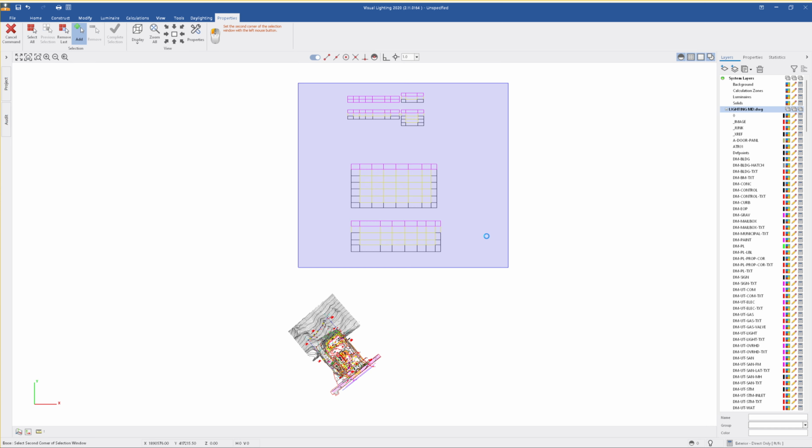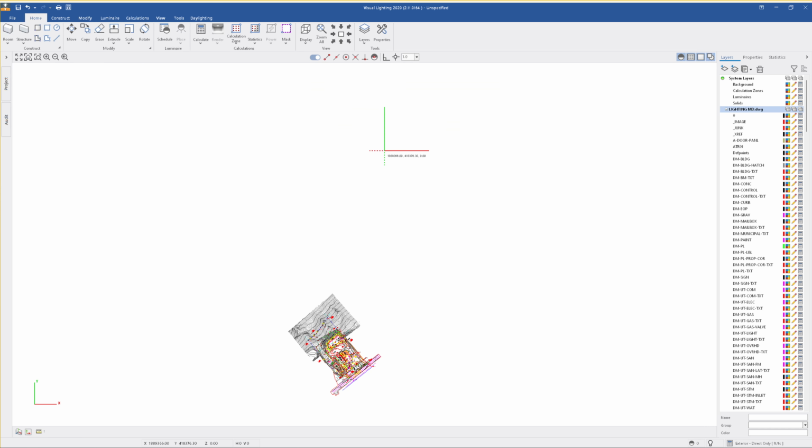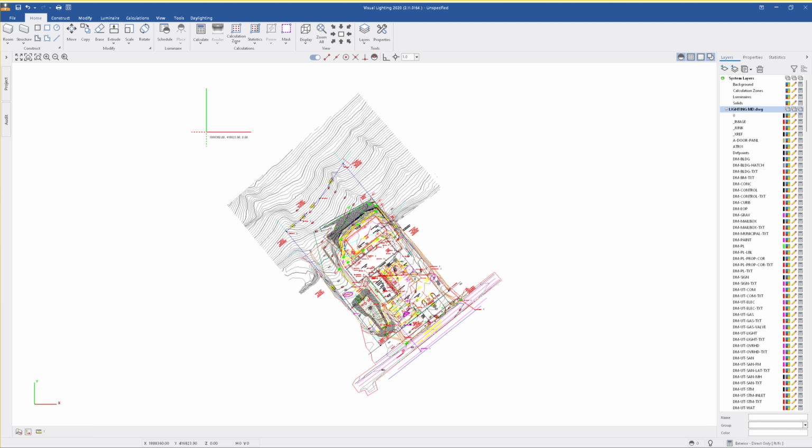But this can be time consuming, or if you're not familiar with the project at all, it can be a little bit of a challenge finding all the items that are left behind. So now we got into here. You'll notice these layers all come in with a pencil. That pencil means that you can edit the layer. So right now it's kind of like freezing and thawing, but for this beginning part, I usually keep those visible so I can actually see what's going on.